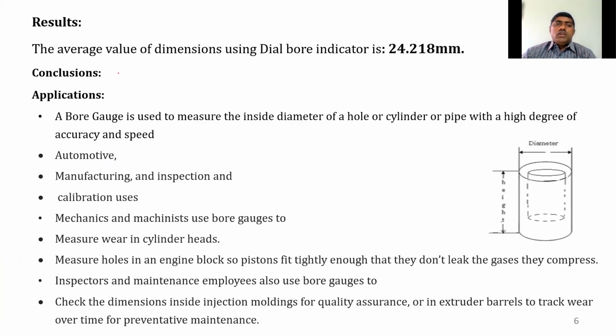Now we note down the average value under the results section: the average value of the dimensions using the dial bore indicator is 24.218 mm. What is the conclusion?